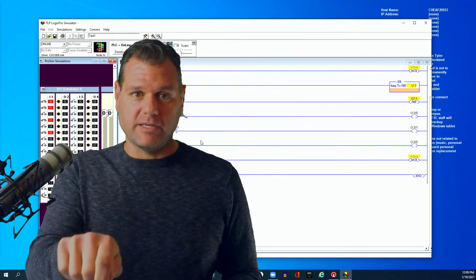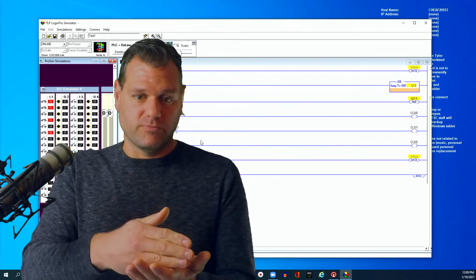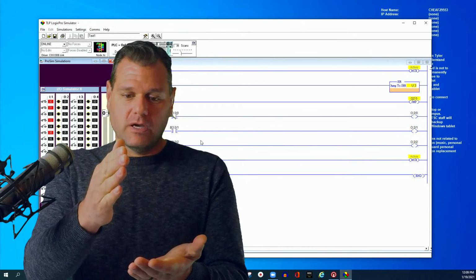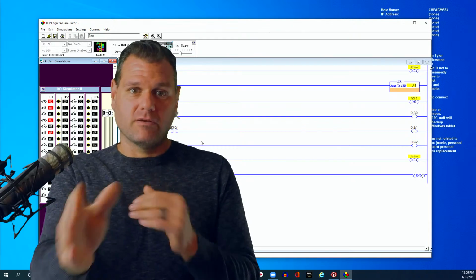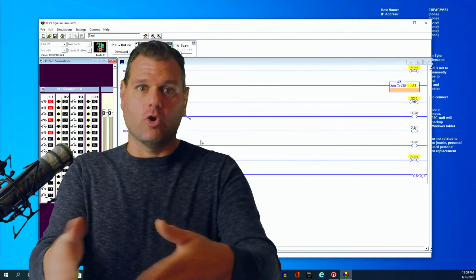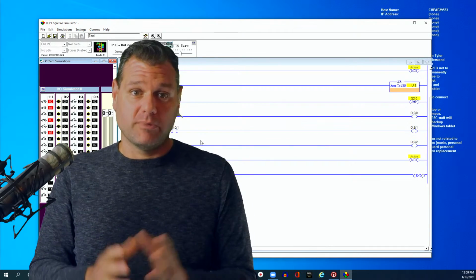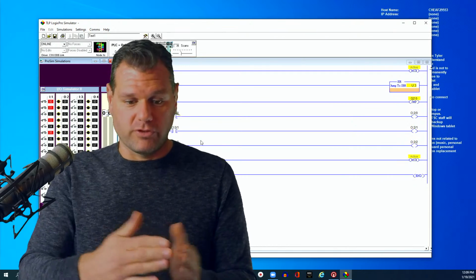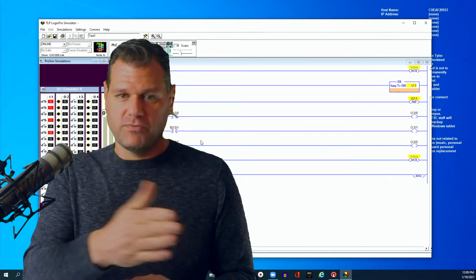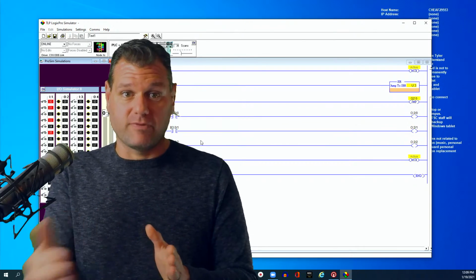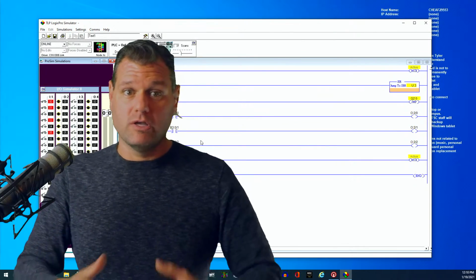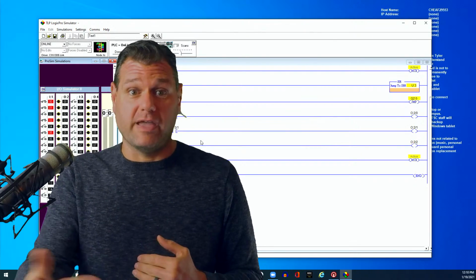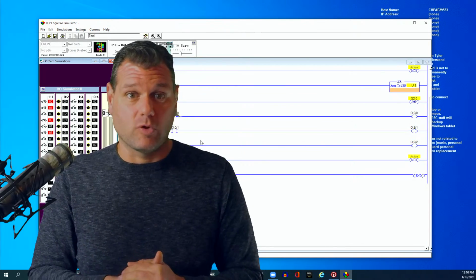So I would put in a maintenance key. I'd stick a key in and rotate it. It would set a mask in place, and the mask would say, okay, you are masking all the doors, so now you can walk over and open the doors, and the machine has no idea, because in the last state before the mask was in place, it saw the doors closed. Even though the switch is open and it sees a 1 now, it doesn't know that. You completely masked it from its destination. So the machine is running as normal because you masked it from the destination. The destination would have been the error, which would have shut the machine down if it had happened normally.